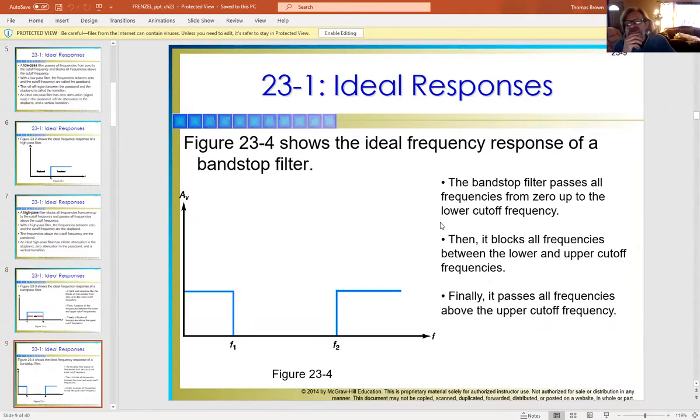And basically the models here, we're going to look at the different types. So the band stop is an interesting one. Now, this is like the reverse side of the coin, where anything between these two frequencies is rejected and anything below or above is allowable. So say we knew that this particular frequency was always going to interject a signal into our signal, and it was an unwanted effect, we could set up a band stop circuit to literally reject anything within that frequency range, and that would just eliminate that signal from interfering with us altogether.